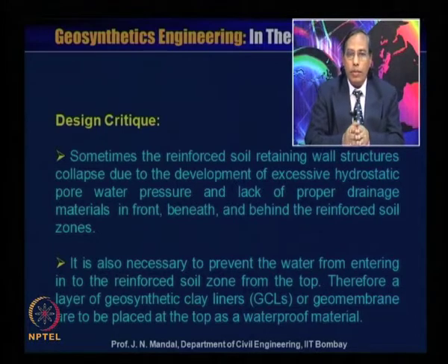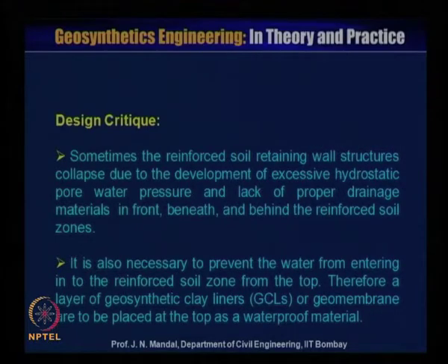So, it is necessary to prevent the water from entering the reinforced soil zone from the top. Therefore, a layer of geosynthetic clay liner or geomembrane is to be placed at the top as a waterproof material. Apart from that, to prevent excess pore water pressure, you need a proper drainage system.